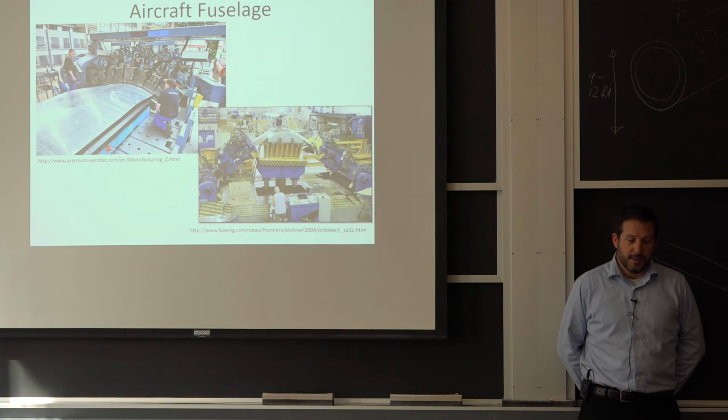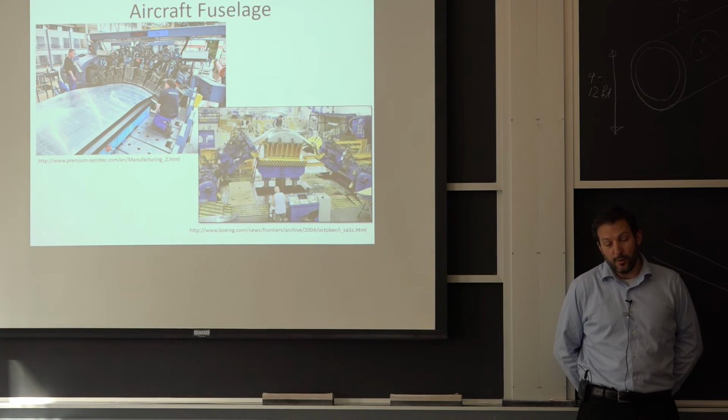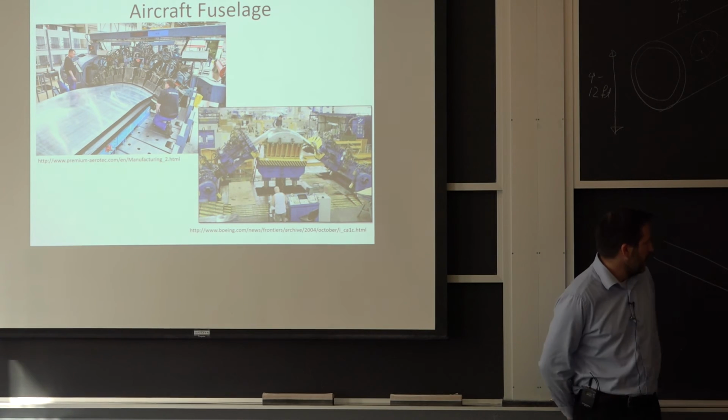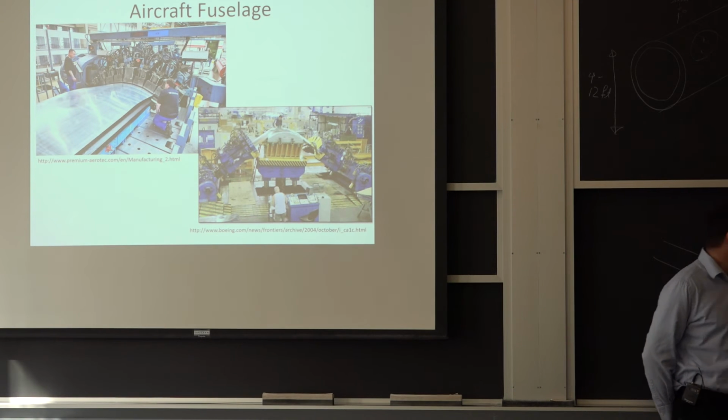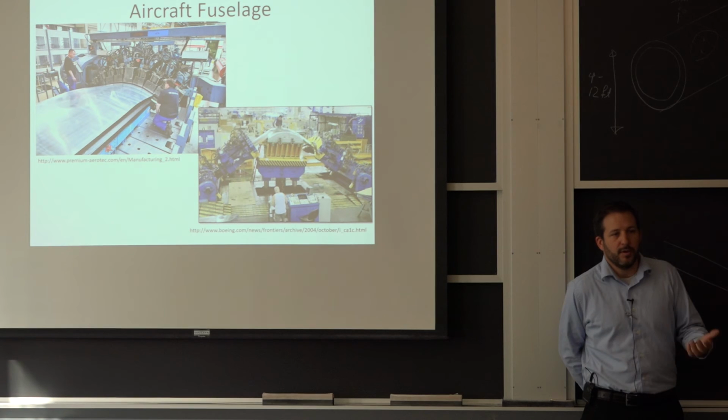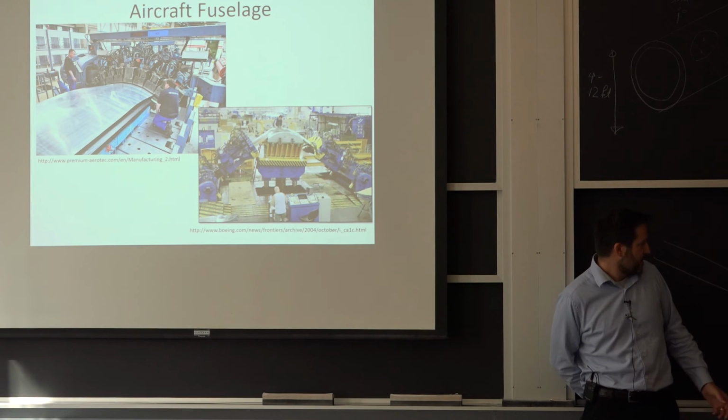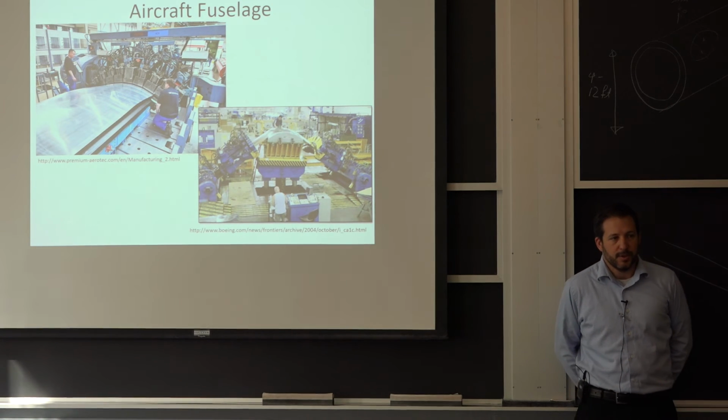So it's not going away. This has been optimized and works very well for reducing your residual stresses, getting your proper heat treatment, and getting a very, very precise shape because you don't have as much spring back when the stress profile is reversed when you unload.